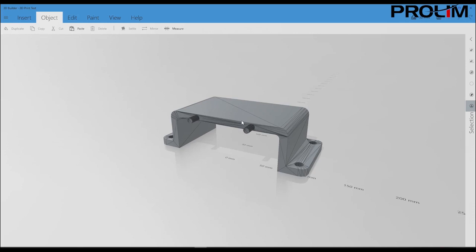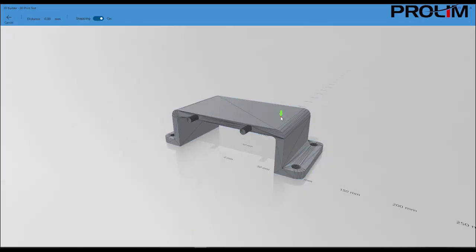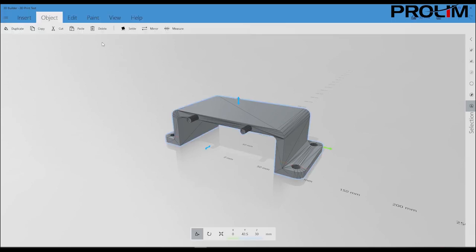And again, we have a couple of options here. We can measure the part. Let's do a height measurement. And once that measurement is applied, you can look up here and it gives you the distance in the top left-hand corner here. And again, it's pretty simple. It can snap to the features in the part. So if we want an overall length dimension, we see it's 220. We've got the overall height. So again, pretty user-friendly here.